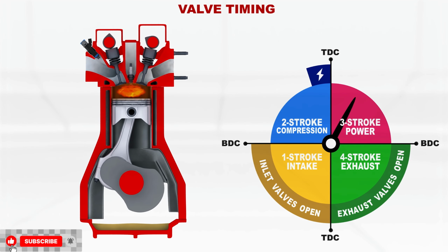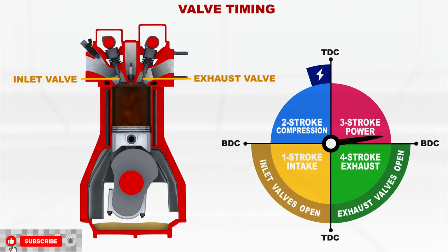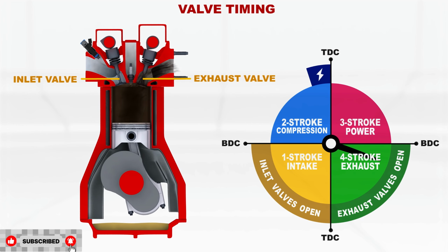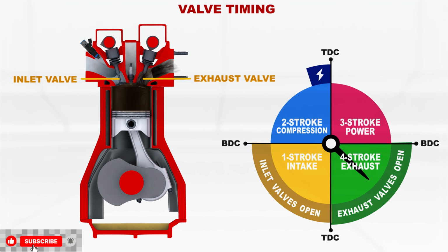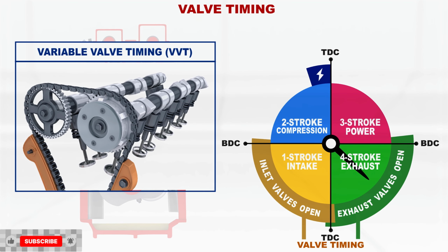Please keep in mind that in order to improve engine efficiency, the inlet and exhaust valves open and close prematurely and delayedly related to the dead centers. The exact timing of the opening and closing of the valves is called valve timing. The optimal valve timing is set during camshaft design and does not change during engine operation. However, if the engine is equipped with a variable valve timing system, valve timing may vary during engine operation depending on the engine operating mode.